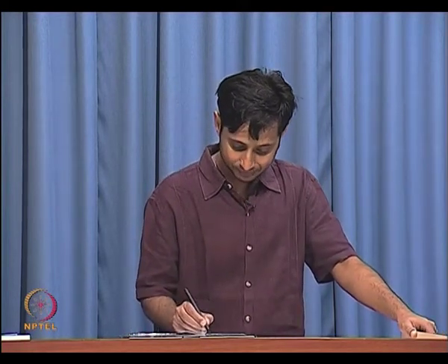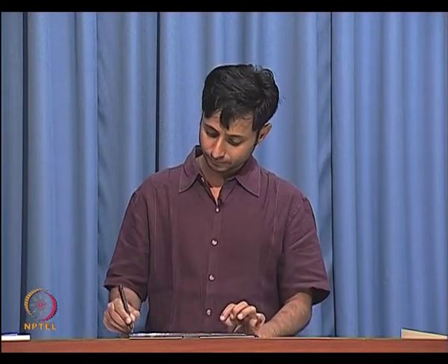Okay. If you have equal spacing between all the metal layers, then you have got 4 times lesser parasitic in this case in the top plate and 7 times lesser parasitic in case of the bottom plate, right. So, you have really won by a huge margin. So, the idea is go as far away from the ground plane, as high up as possible from the ground plane. Do not be close to the ground plane, because that is going to create parasitics, right. Okay. What else can you do?